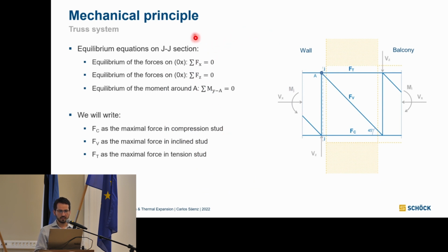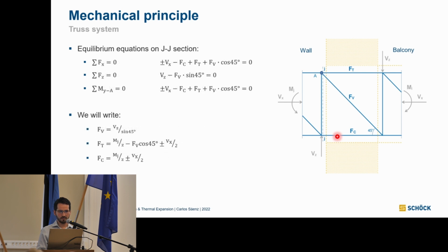And yeah, okay, we can write the equations and everything will be equal to 0, because of course the system is balanced and nothing is moving. So yes, here are all the elements for the principle. And when you write the equations, you develop them into terms of the acting force. So you get the forces that each of your studs needs to withstand.